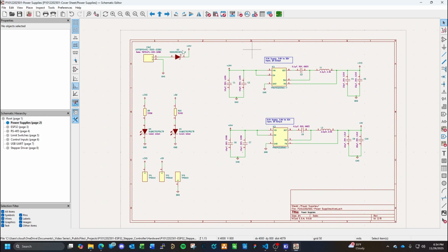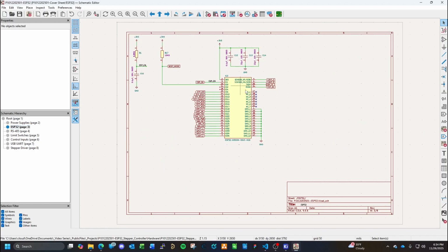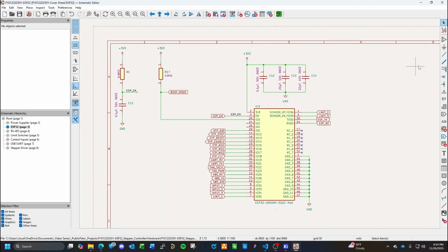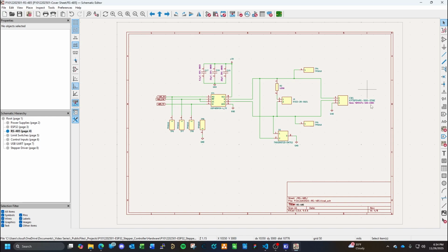Okay, we got our inputs. We got our voltage rails tied in there: 5 volt, 3.3 volts. That's the 03 version. That's the 05 version. We got LEDs, test points, ESP32. Let's go ahead and throw in these not connected directives for now. Again, this is the first spin, we should be fine. 3v3, 3v3, 3v3. That's the enable. Just a real quick overview, a quick sanity check to make sure things are here.